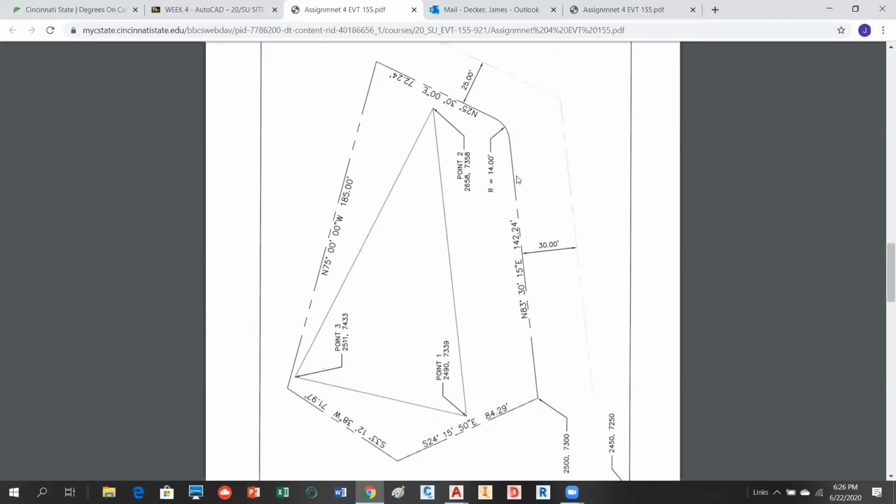And when you want to do the fillet, all you're going to do is set your radius equal to 14. That's right. So if you have a chance to use a fillet instead of an arc, just never use your arc. Okay. Gotcha. Yeah, just don't do it.